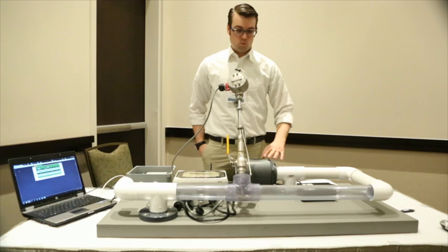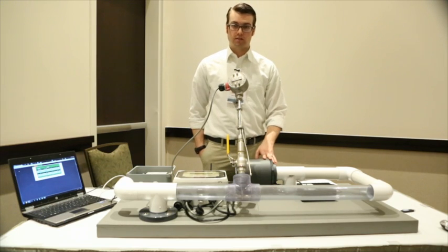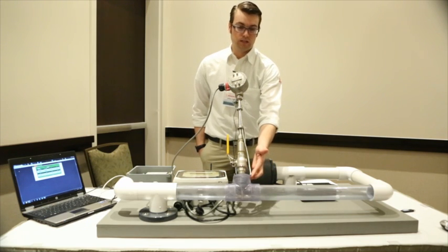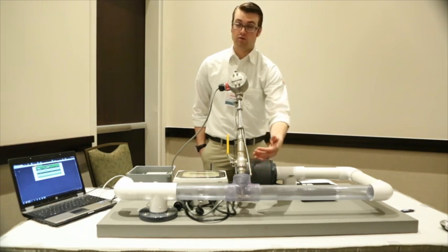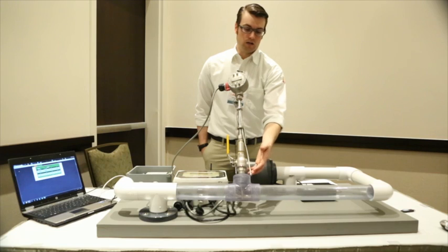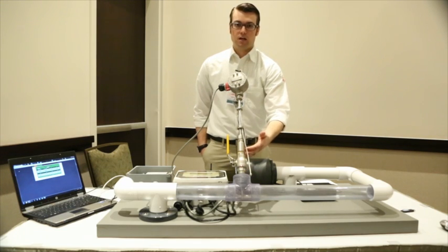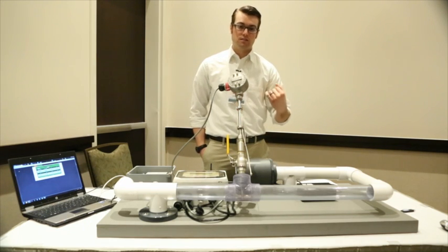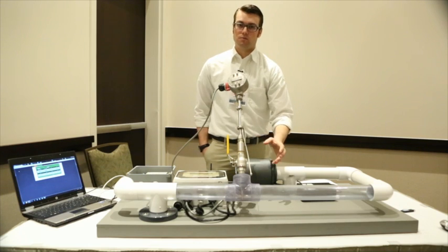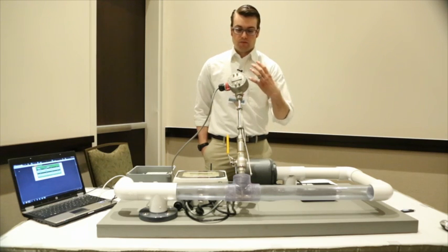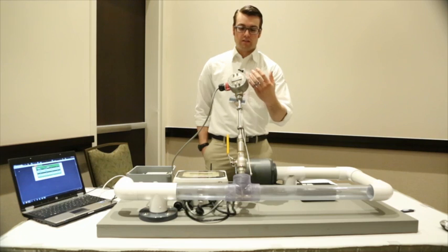So if you have a pipe that you'd like to measure the flow through, you're going to need to weld a weldlet onto the pipe. You're going to have to hot tap the pipe. You can also do it when there's no flow, for example, during a shutdown. You want to attach a ball valve here, some sort of isolation valve, so that if you ever need to take the flow meter out for maintenance, you can just close this valve and you're done with it. You don't need to worry about gas escaping.